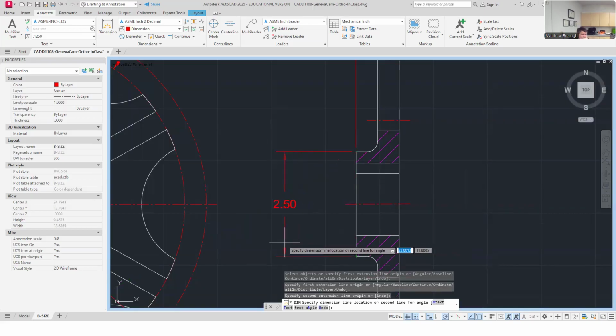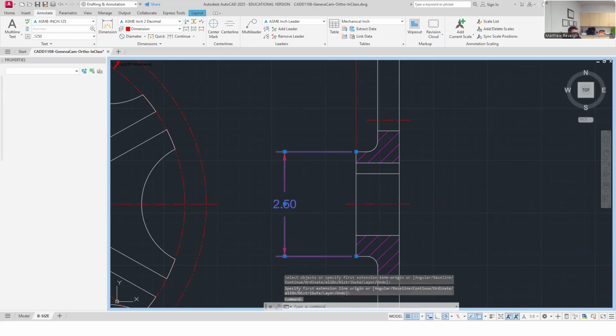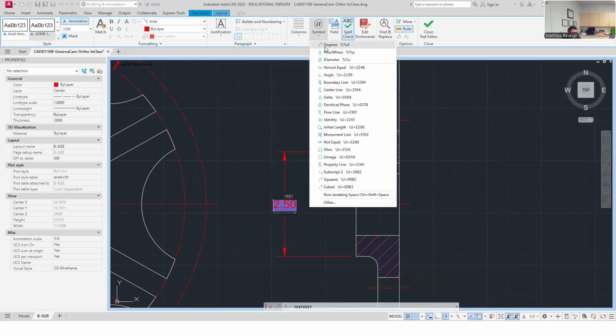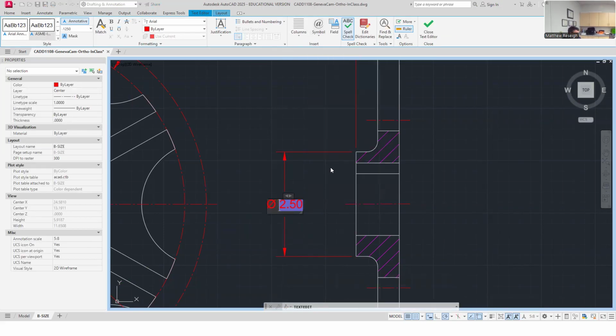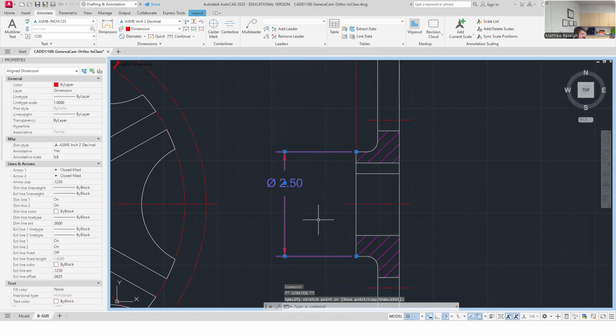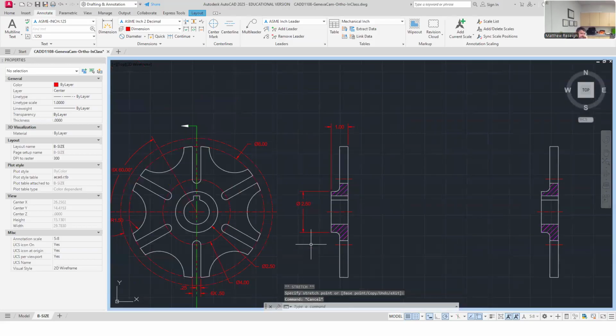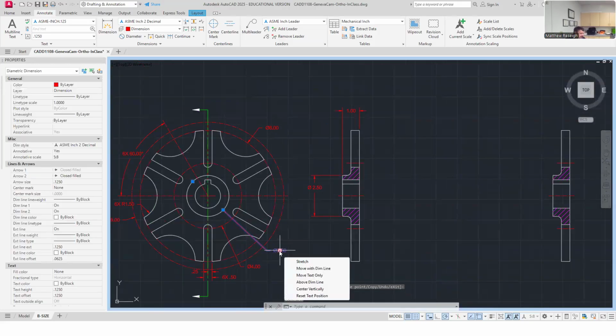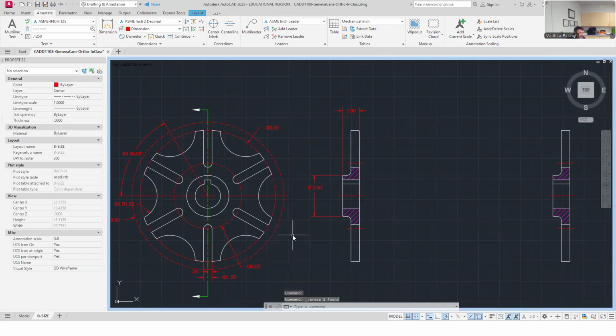Rectangular view, that's kind of the kicker for ASME. We like to do this. And this is a diameter though, so I need to add the diameter symbol in front of it. Diameter. So I'm going to forego this one. I say that's good, but I think the one I did second is best. So I'm going to delete that one. This is a better size.